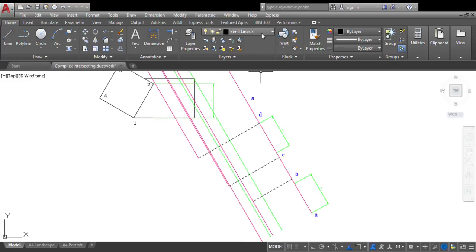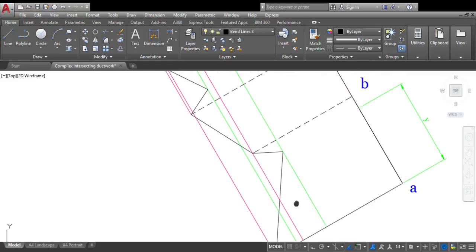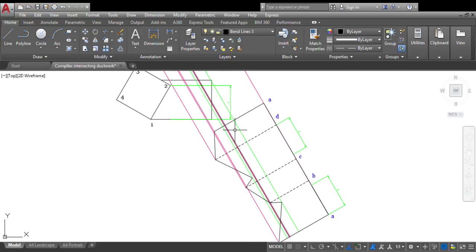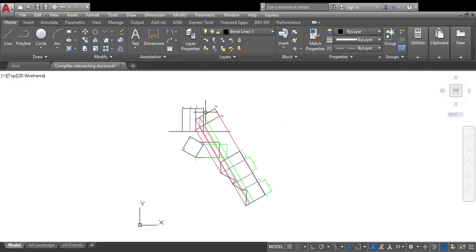So then if we then finally turn on our type 4 lines, we can see that these are where, using these construction lines from plan, we can show the pupils where these principles are coming from, and where these heights are stepped off, and where to join back to. So that means we can show these principles, without complicating the drawing, by the horizontal lines coming from elevation over to our development of the square base section.